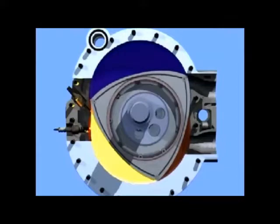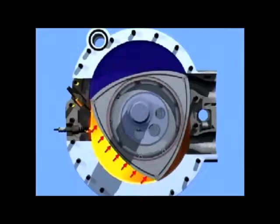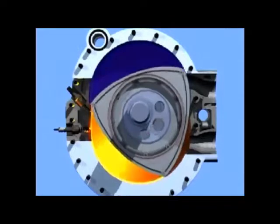Then comes the 3rd stroke, the expansion stroke. Here, the ignited mixture exerts pressure on all sides of the combustion chamber. The side created by the rotor is hereby forced to move to allow the mixture to expand, forcing the eccentric shaft to rotate. This rotation of the shaft is then the driving power of the motor.